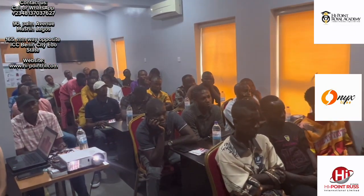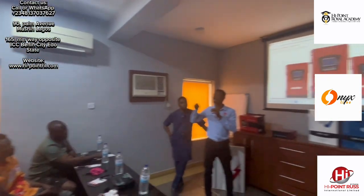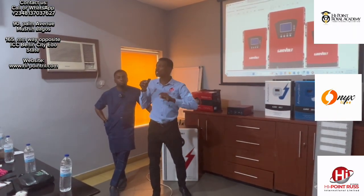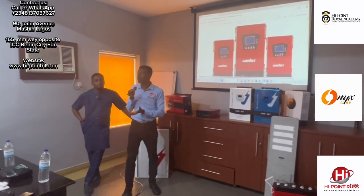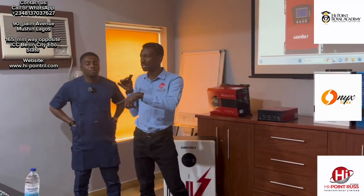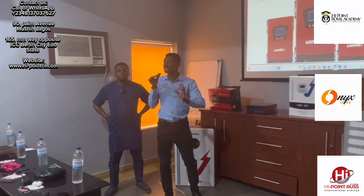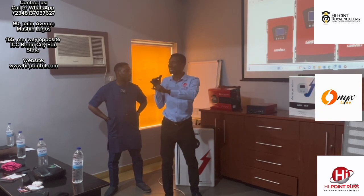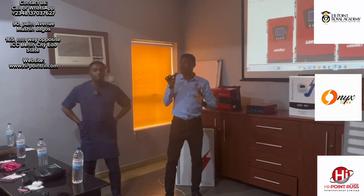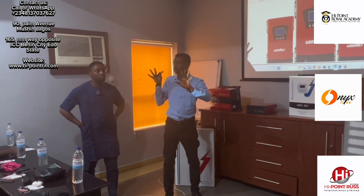But what you just need to take note of is that the voltage of the battery system you are using must be compatible with that appliance, that light bulb, that solar fan. It's not that you are charging a 24 volt system and then you want to plug in a 12 volt light bulb or 12 volt fan. It will damage it, because you are feeding it too much voltage. So the best thing is to check that the voltage of the appliance you want to power is 12 volts, the same as the battery bank voltage. If it's a 24 volt battery bank and they are not equal, you can desist.